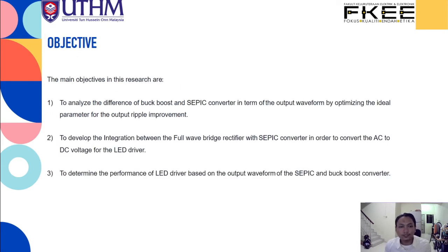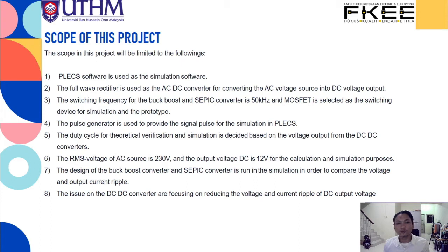Okay, for the objectives, the main objective in this research is to analyze the difference of buck boost and SEPIC converter in terms of output waveform by optimizing the ideal parameters for the output ripple improvement. Next, to develop the integration between a full wave bridge rectifier and a SEPIC converter in order to convert AC to DC voltage for the LED driver. And finally, to determine the performance of the LED driver based on the output waveform of the SEPIC and the buck boost converter. The scope of this project will be limited to the following.